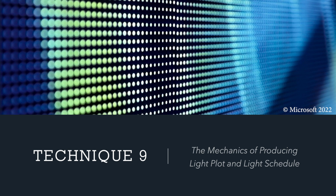Technique 9. The mechanics of producing a light plot and the light schedules. This episode demonstrates how to create a symbolic light plot and generate paperwork of an instrument schedule and a color schedule from a light plot in Vectorworks.